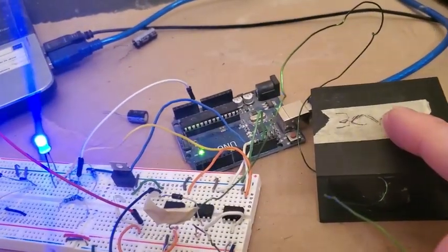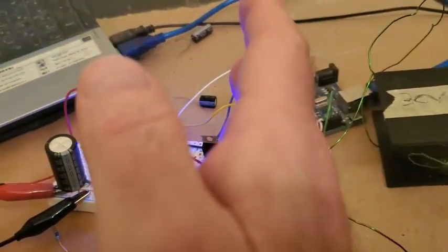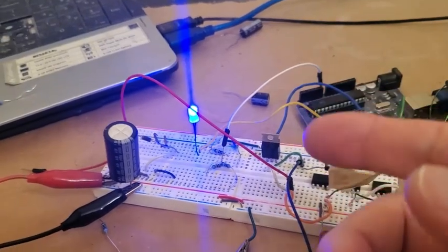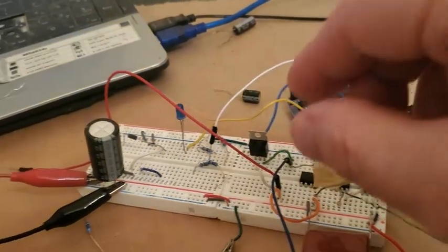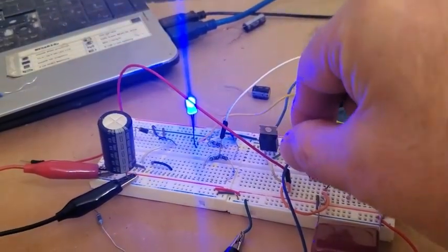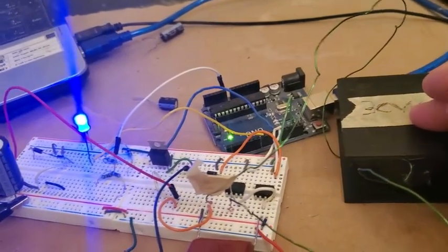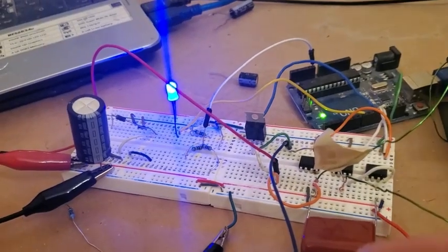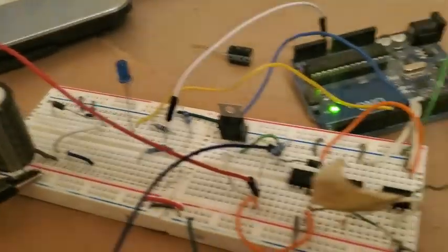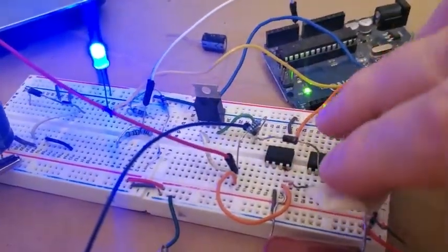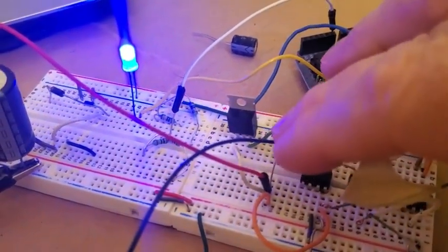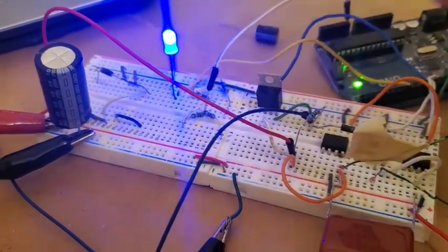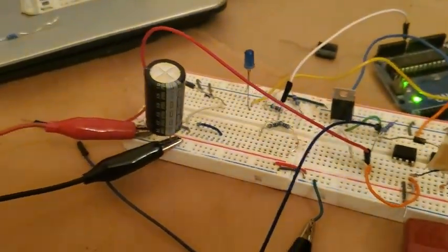When this thing is loaded, drawing power off, it draws less power than when it's not loaded. So at first I thought, well, maybe the voltage in this cap is somehow interacting with the impedance of the coil. Then I got the idea, let's just put in a purely resistive load. So now I've connected back up the diode, and I put a 100 ohm resistor across where the cap would have been. So now it's a load with 100 ohms of resistance.